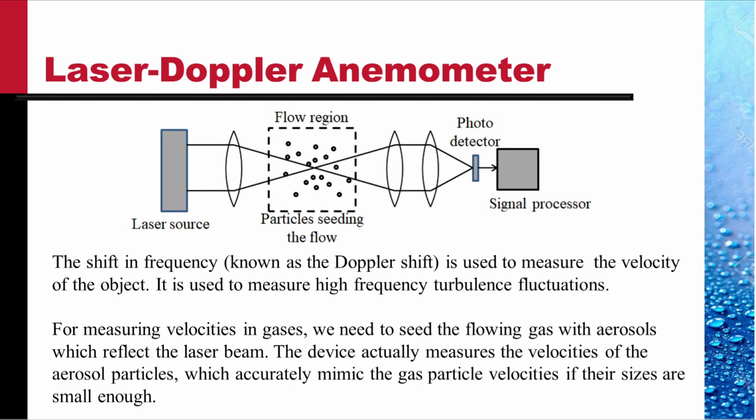Another device is based on the Doppler principle. The Doppler principle states that the frequency of the waves traveling through the medium changes as the flow velocity changes. This is known as the Doppler effect. The shift in frequency is used to measure the velocity.